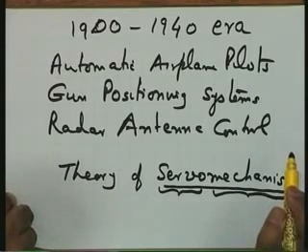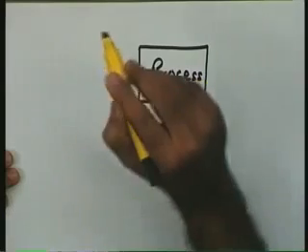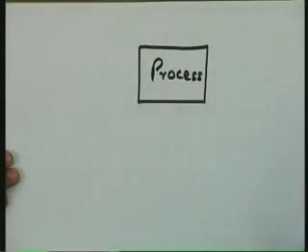Well, the theory of cybernetics, the theory of servo mechanisms, the process control, all these are converging now, and a unified feedback control theory has emerged. And the terminology I am going to refer to is the terminology of unified feedback control theory, meaning thereby it is applicable to all the three subfields I have mentioned. So, in the basic terminology, let me first take up a block called the process, or as we have said, it could be termed as the plant as well, or a controlled system.